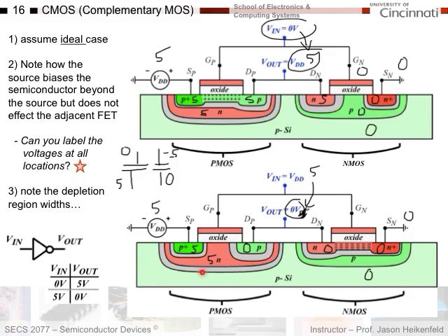And the other thing I want to note about this before we leave this slide is that this shows you how you make MOSFETs. You basically take one substrate, and the first thing I will do is diffuse in my N-type region over here and my P-type region here with the exact doping levels that I want to have the right threshold voltages and good MOSFET properties.